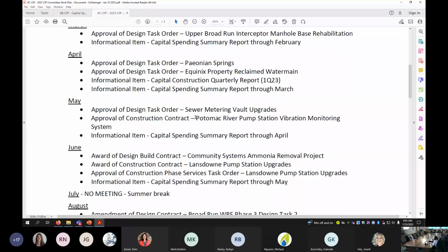As you recall, these are open line bearings, and so they're being lubricated by the liquid that is being pumped. Sometimes if the liquid has a lot of debris and material, it can erode either the bearing or the shaft. Since we replaced the bearing material and hardened the shafts, we seem to be having no problems right now.